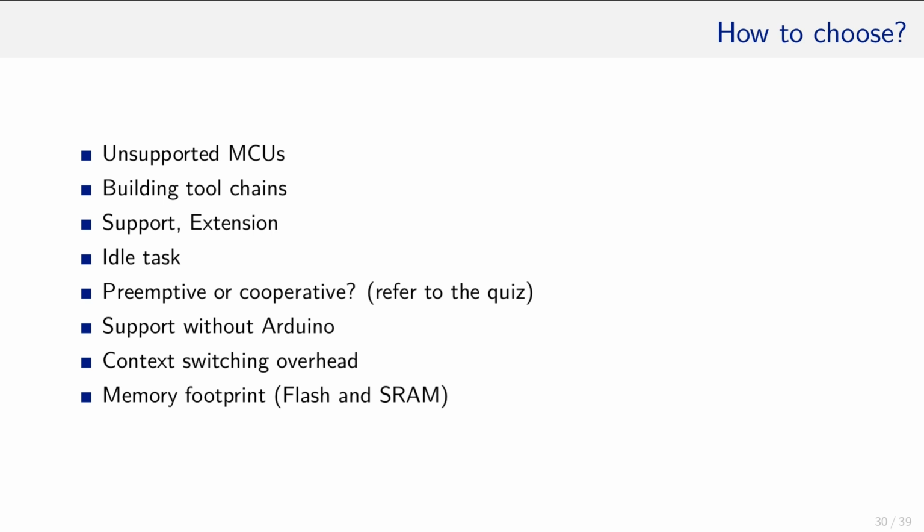It will be tedious work to adapt one of the schedulers designed for the Arduino IDE to run without this library. And apart from a small memory footprint in SRAM as well as flash, it would be an advantage if the scheduler could set the ATmega to sleep if there are no tasks ready at the moment.